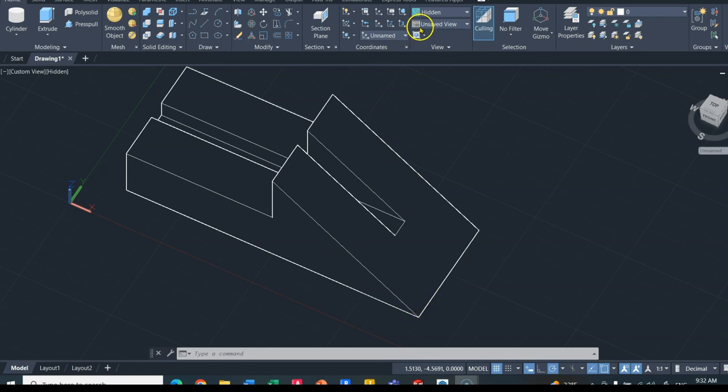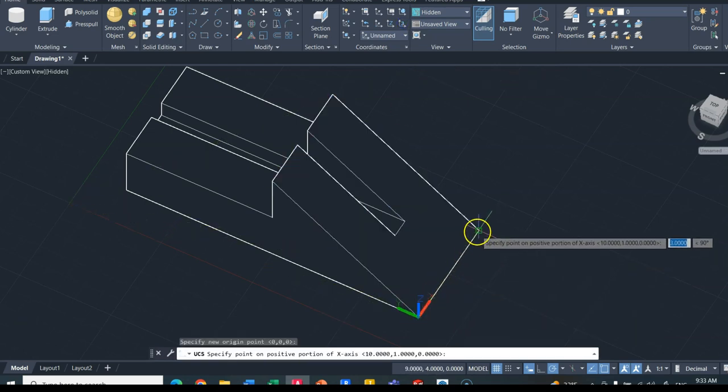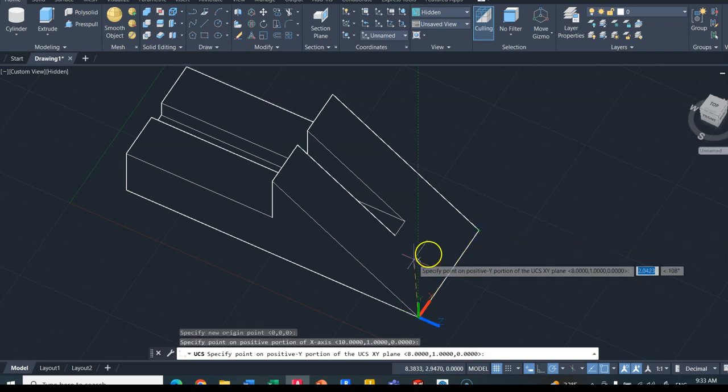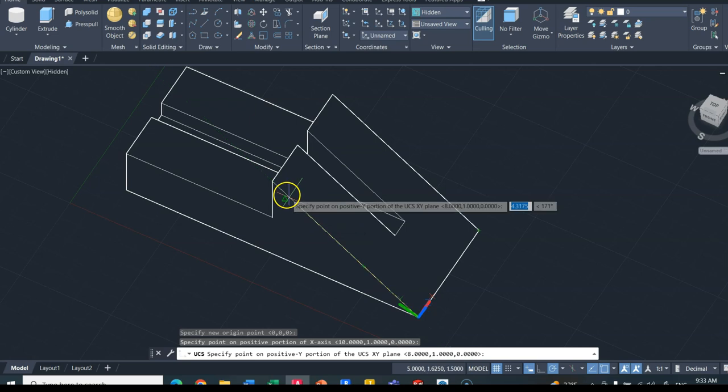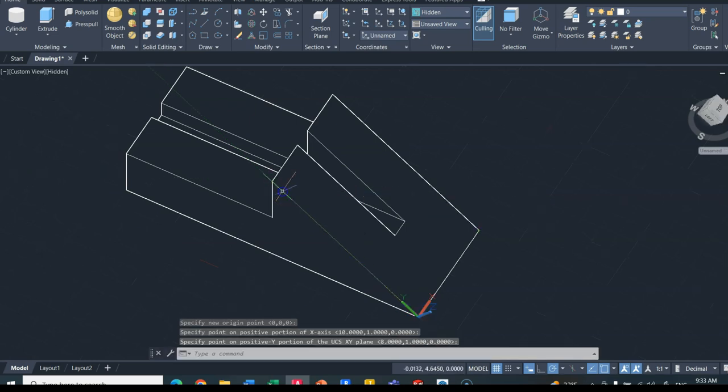For the next step, I recommend having the coordinate here aligned with the face. There are several ways, but I recommend having this 3 to move the coordinate to this point. So let's click on 3 points, align that 3, pick point, make sure the X is aligned to the horizontal line and the Y is aligned to the diagonal line, like this. So you have the X, the red and the green aligned carefully.